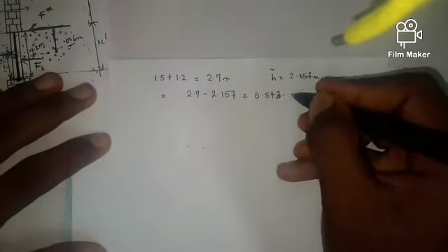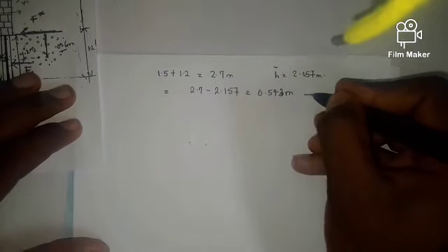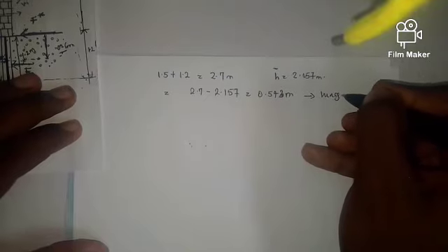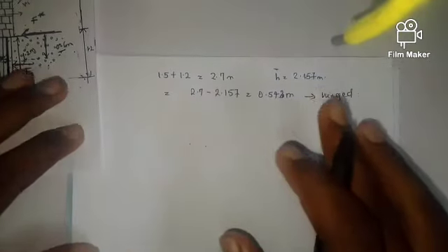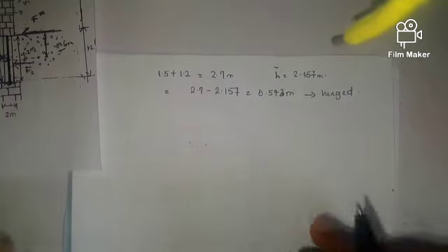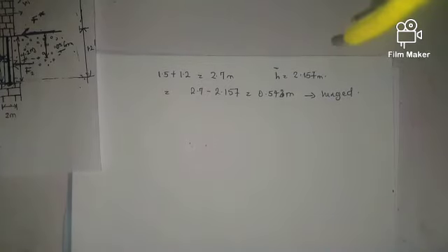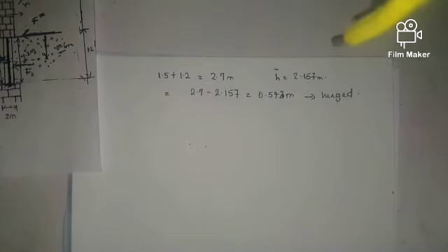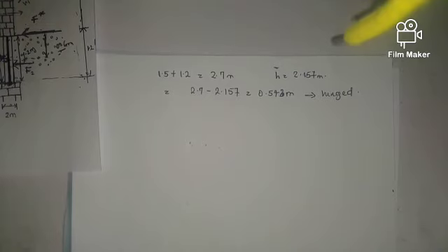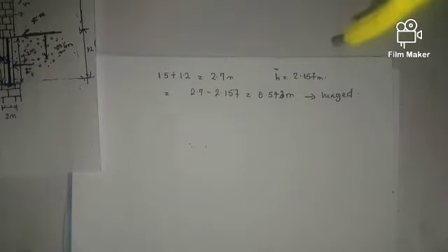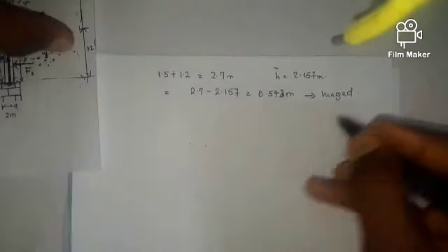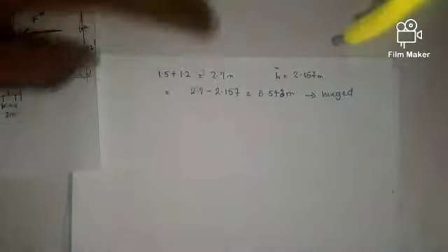If you give me 0.543 meters to the hinged part. Now you're going to see why I'm calculating the distance of F to the hinged part: I want to take moment at that hinged part, because the hinged part is what the force on one side of the liquid and the force on the other side of the liquid have in common. So then I can calculate my horizontal force. So this is the 0.3 meter to the hinged part.